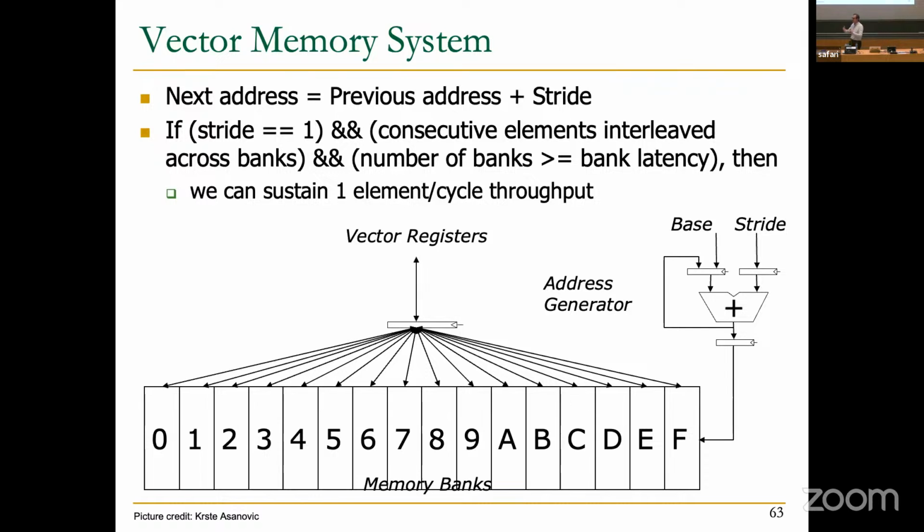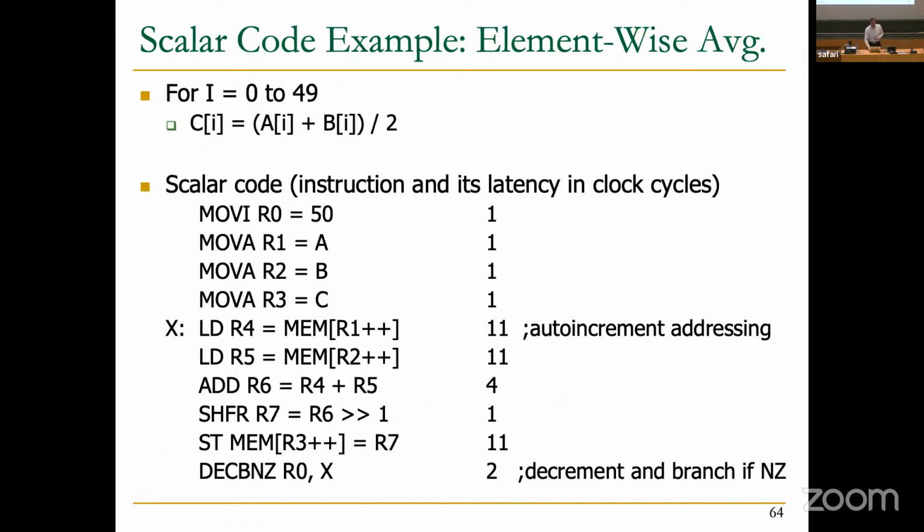It's not really mapping of operations to functional units. It's really mapping of data to memory banks. And if you mess this up, everything else is messed up in a vector processor, including a GPU. If you're programming a GPU, how many people program GPUs here? Okay, you know the importance of this probably. Data mapping, somewhat. Okay, depends on what kind of performance you want to get. If you want to get the highest performance, this is really extremely important. And we will see this soon again.